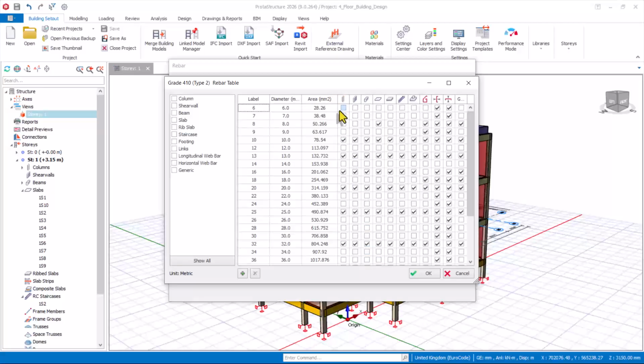For the concrete column, the minimum rebar will be 16 mm diameter. We don't have walls in this system, we have beams, so the minimum reinforcement diameter will be 16 as well for the reinforced concrete beam. For the slab, our minimum is 10. Also check 12, and we get rid of 13.